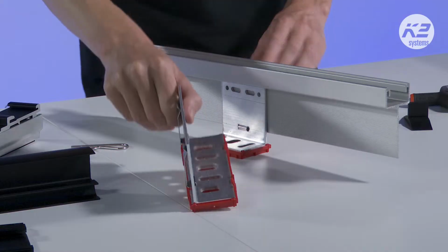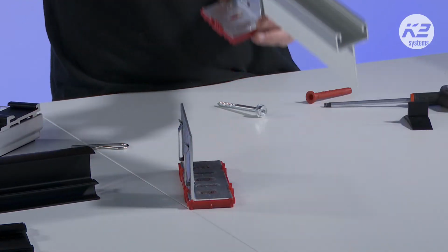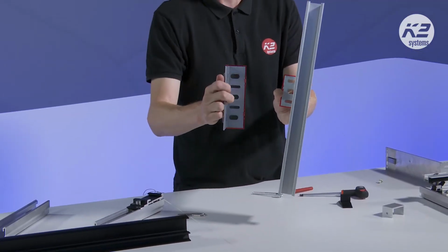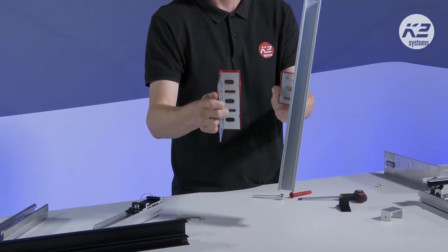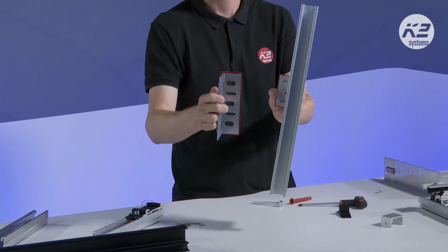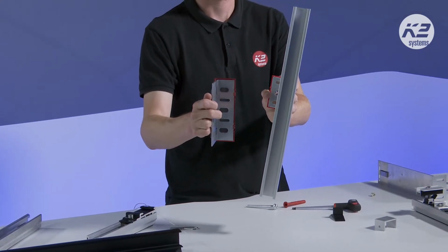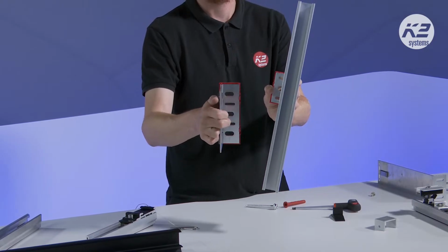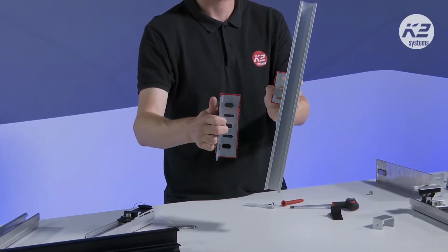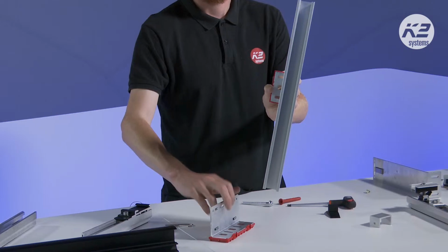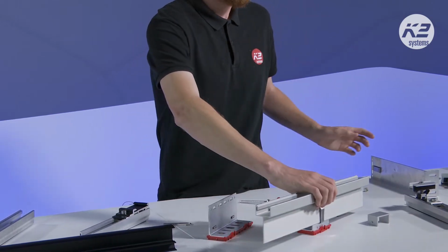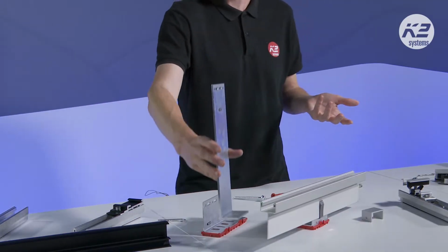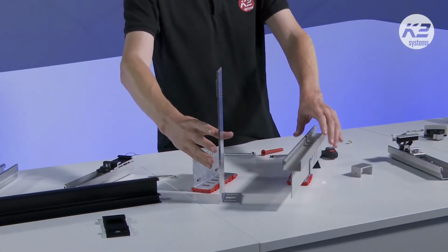It's also, if you think about it being placed vertically, as it's longer, if there's any pull down, it's going to be better distributed on the top. So while it's longer, there's less bending moment moving forward, or let's say more resistance to the bending moment pulling forward. And we also have the option of installing with different lengths of insulation, right?